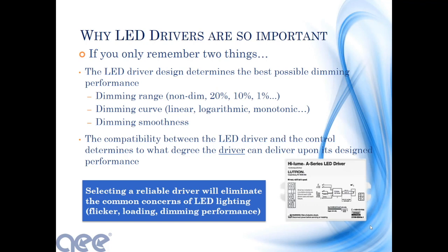And then we've talked about the dimming curve already, and then the smoothness as well. So there is the point where you do have to make sure that the driver is matched up and coordinated with the LED engine like we talked about. And selecting the right driver will eliminate a lot of what we're talking about on the flicker, all those types of things, dimming performance, that type of stuff.